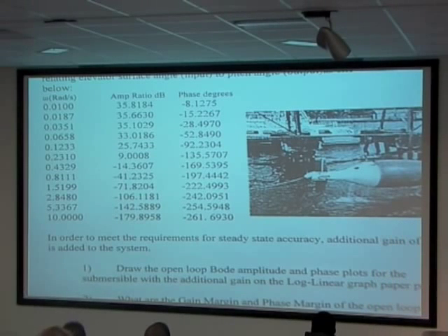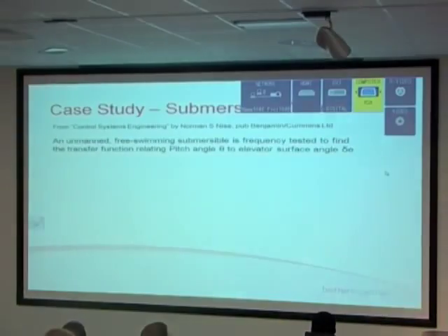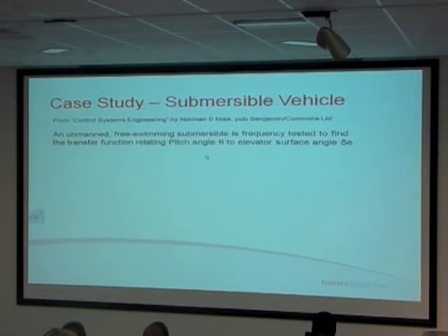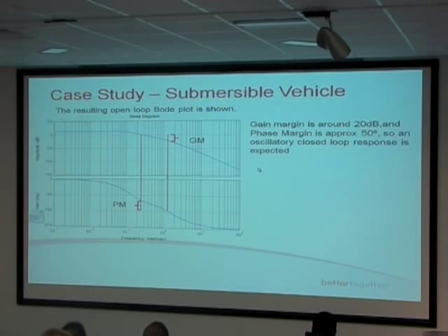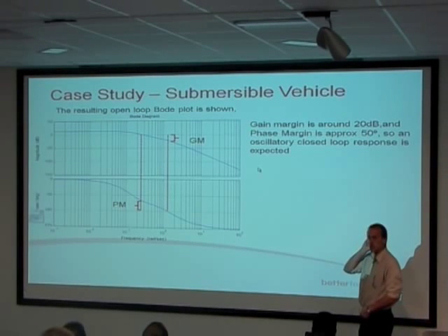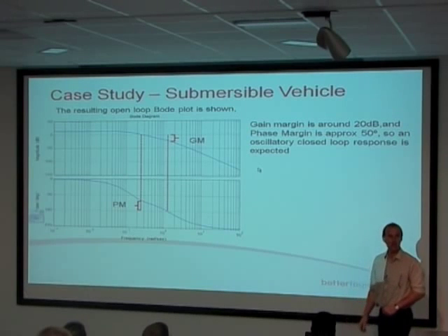Why am I interested in that? Well, what I'm looking at is the output, which is the pitch angle of the vehicle, theta, relative to the elevator surface angle, delta E. From that experimental data, I can construct an open loop Bode plot and have a quick look at the gain and phase margins.